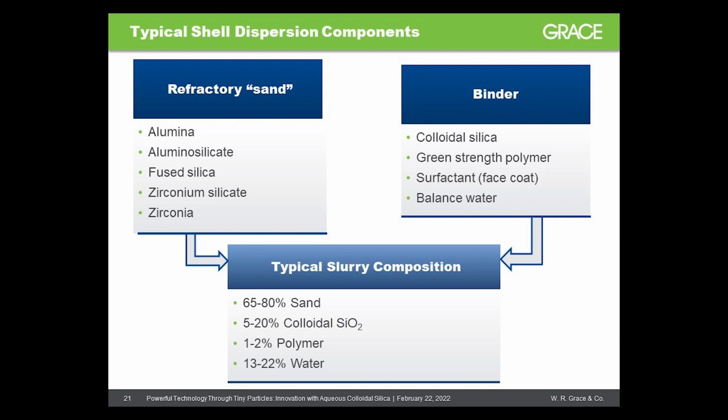In addition to the colloidal silica binder, other minor components can be added, such as polymers and surfactants, to aid in green strength and in the wetting of the wax substrate. The actual amount of colloidal silica in the system that results in ceramic casts of maximum strength depends on the particle size of the colloidal and can represent up to 20% by weight of the system.